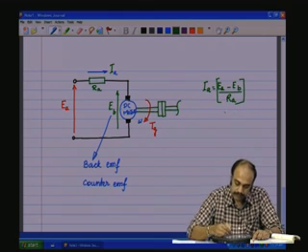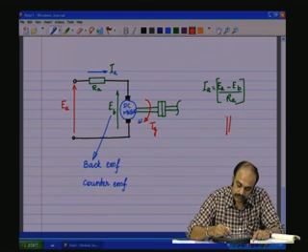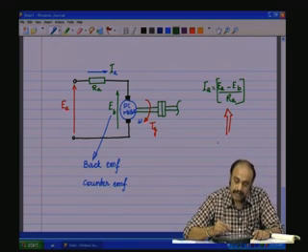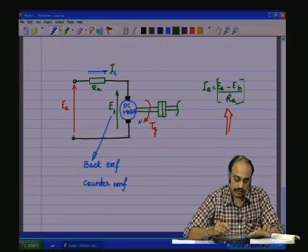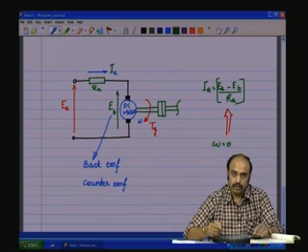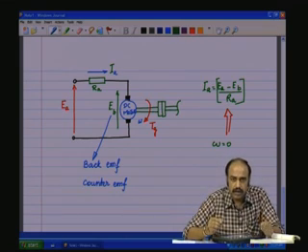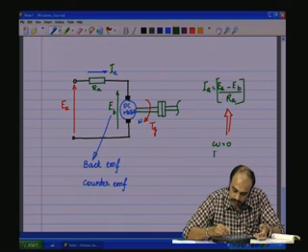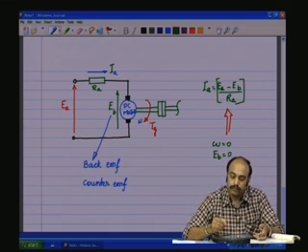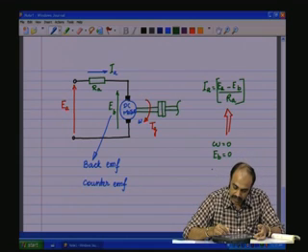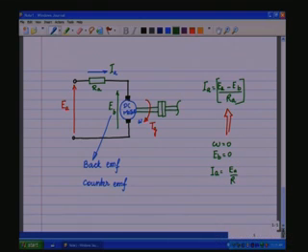It is an interesting relation. What happens at the start? So, let us say you are powering on, the shaft is not rotating, omega is equal to 0. At the moment it has powered on, the shaft has still not picked up speed, it is starting from 0, omega is equal to 0, and therefore, EB or the back EMF is 0. So, the whole applied voltage is going to come across RA, and therefore, IA will be EA by RA.